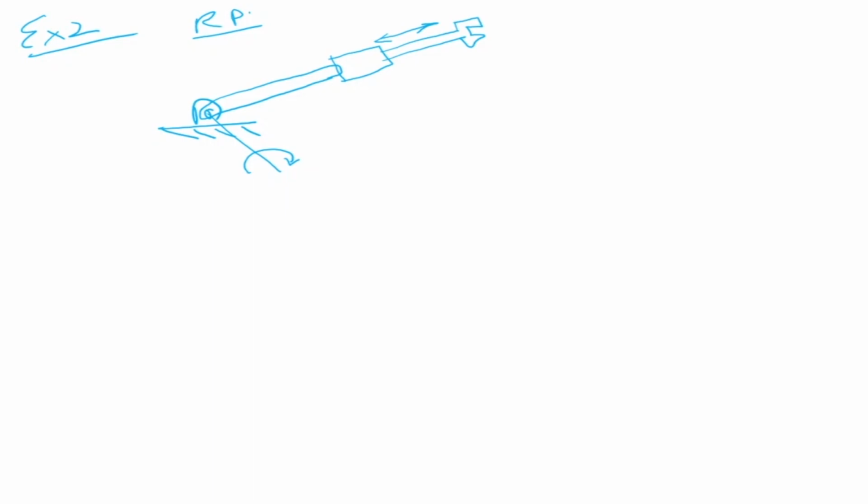Let's put our DH parameters. So I can put my z0, z1 here. So x0 is there and x1 is here as per DH. So this angle is my theta 1. And let us say this is my m. So this is the distance. L1 is the distance from here to here. And this is a prismatic joint, so this can move back and front. So let me say this full distance from here right till here is my d2. So this is my d2.